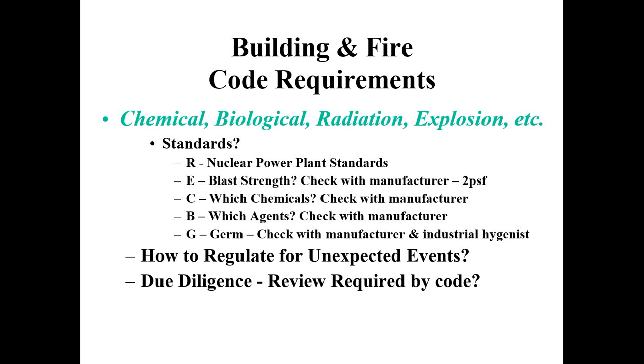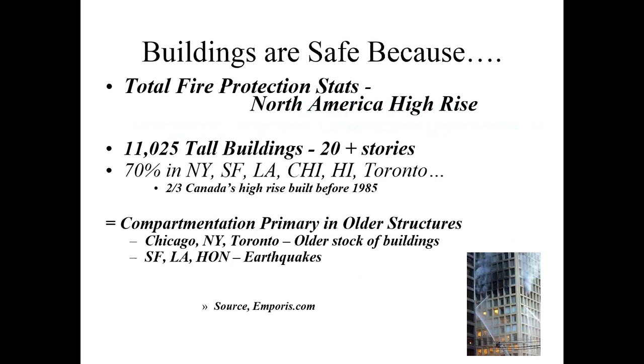Maybe there are latex products that will do that. Maybe there are non-silicone-based products that will do that too now. Check with the manufacturer. Let the manufacturer's industrial hygienists who write the MSDS sheets, the safety data sheets, SDS as they're known now, work with the building owner's industrial hygienist so that the two of them come together to say that germs won't spread or biological agents won't spread. That due diligence should have been done before the contractor shows up on the project. That way, the specifications are very specific about what could be used for those types of applications.